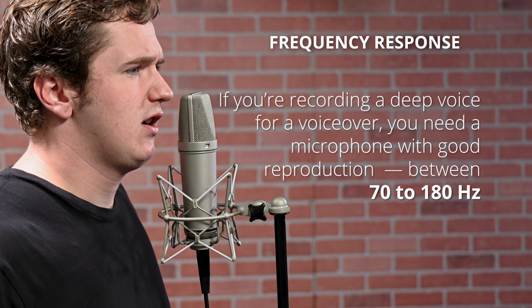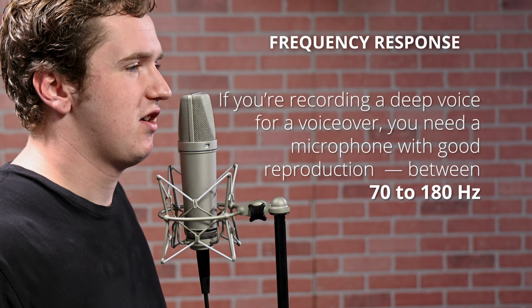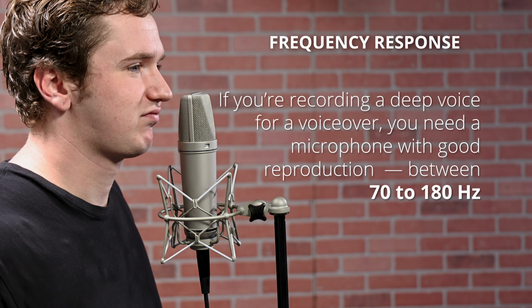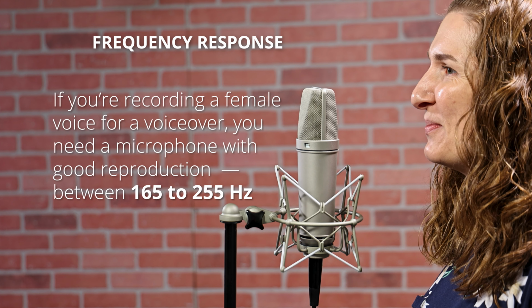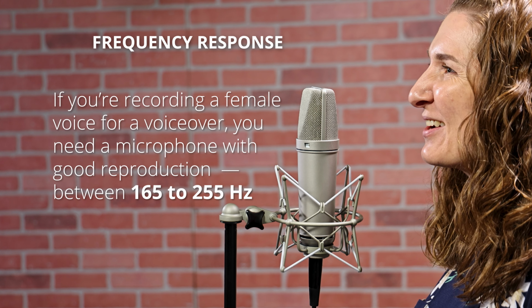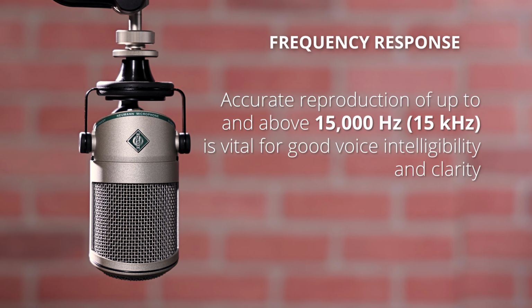For example, if you're recording a deep voice for a voiceover, you need a microphone with good reproduction between 70 to 180 Hertz. If you're recording a female voice for a voiceover, you need a microphone with good reproduction between 165 to 255 Hertz. Keep in mind that accurate reproduction of up to and above 15,000 Hz is vital for good voice intelligibility and clarity.